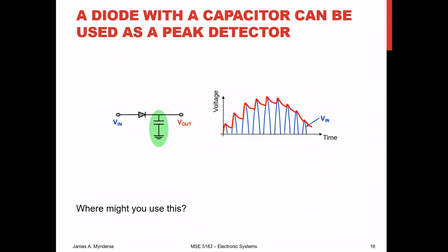You might see another version of this where you put in a couple of op amps. So I will draw those in real quick. In the op amp configuration, we put in V in here. We'll tie that out to here. And so now we've got this follower after it, and we've got the input op amp as well. I took this from planetanalog.com. I thought they had a good explanation. So again, the input is going to charge the capacitor, and the diode is going to then prevent discharge of the capacitor, and it'll keep that peak value.